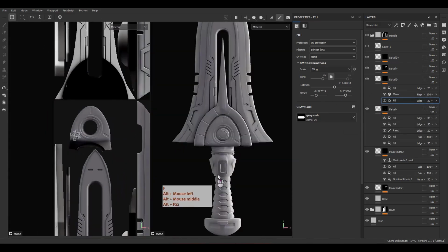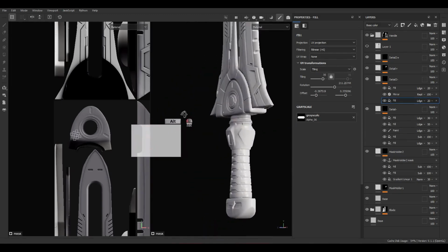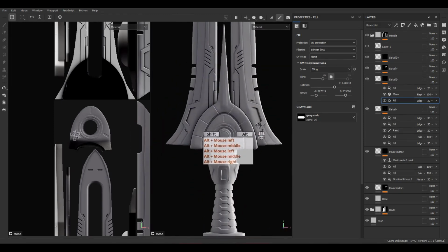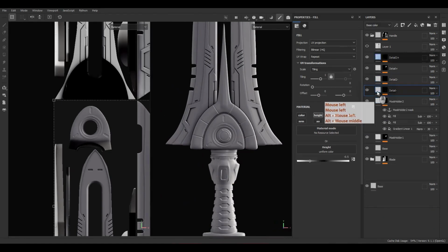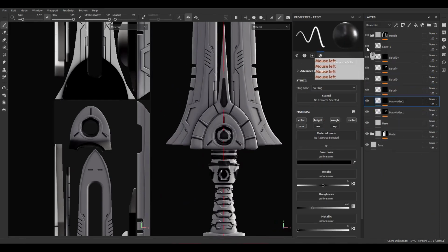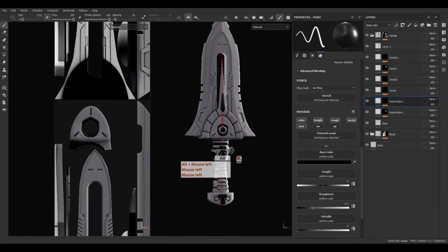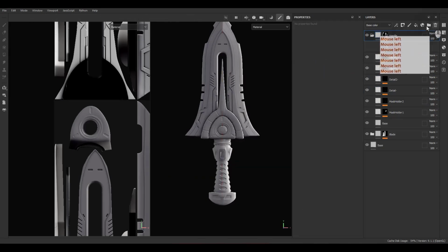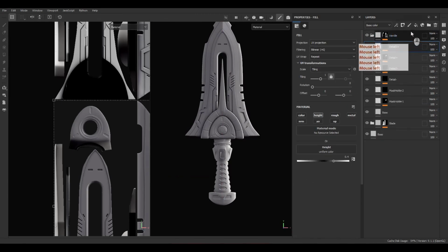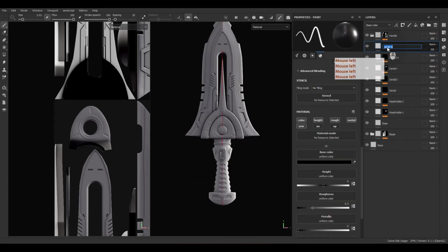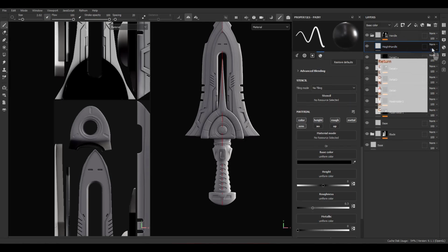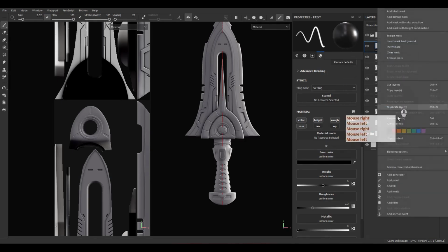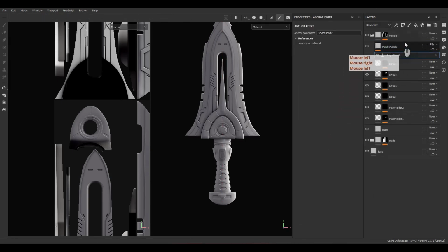So this is what we have right now. Yeah, I think it's okay. Let's go back to our sketch, and we achieved what we want. And for the final step, we are going to add a paint layer and call it height handle. Change the blending mode to pass, apply to all channels, and add an anchor point.